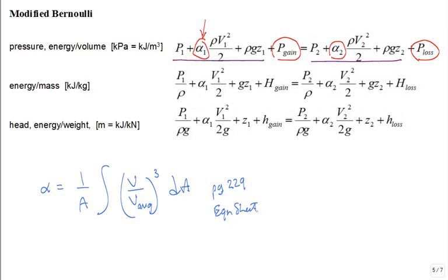And thankfully, it's almost always 1, and you can assume it's 1, and often we're neglecting viscosity and frictional effects. Hence, it's going to be in the noise. But this is your pressure gain or your pressure loss due to some restriction or something that's creating that loss. If it's a gain, it's typically due to a pump, some device that's putting mechanical energy into the flowing fluid.